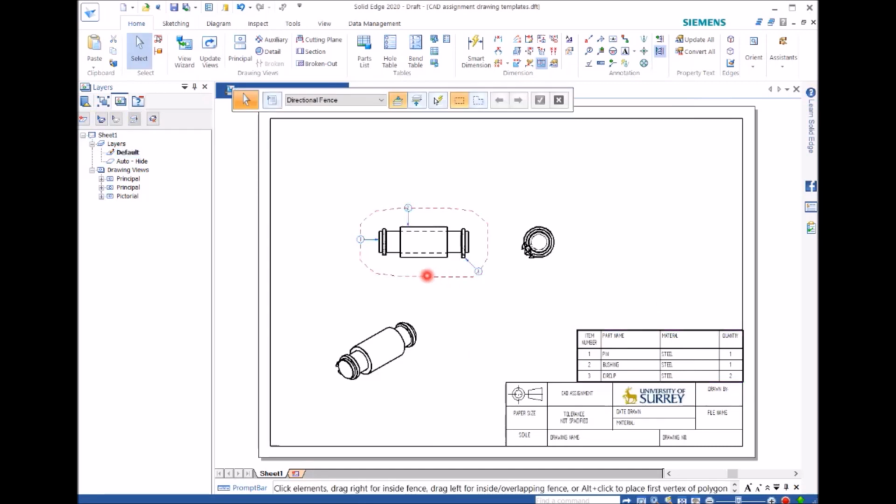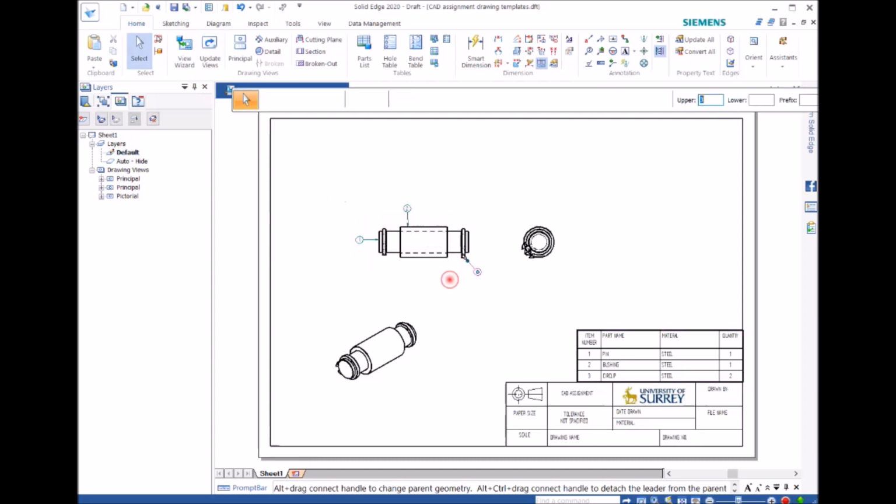You can click on this dotted line and remove it. If you don't remove it, you can drag the dotted line and the other balloons go with it. If you want to set them free individually, you can click on the dotted line and press delete. That will be deleted. From now on, you can only drag the numbers one by one. Make sure these numbers run clockwise.